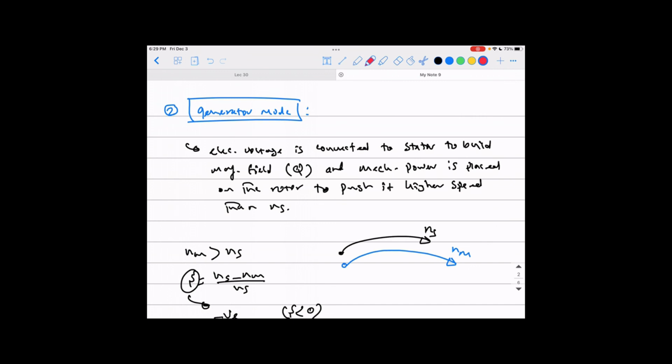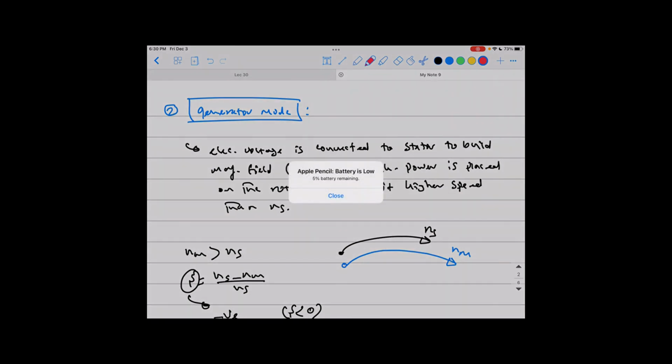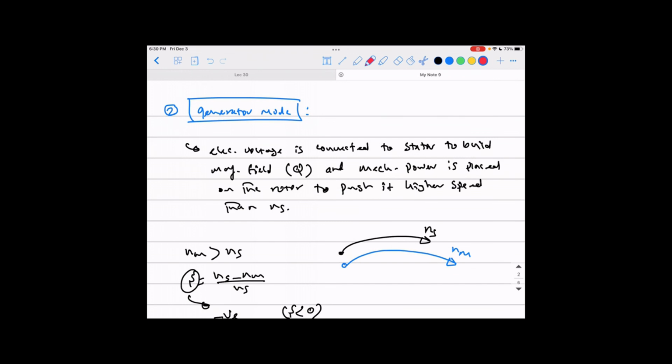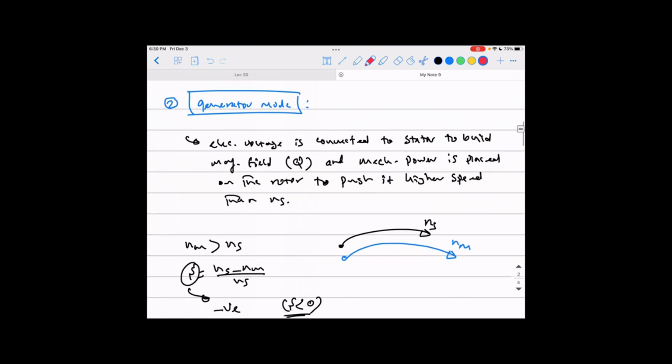It acts with almost the same theory of operation, but it's different because you have two sources, one on the stator and one on the rotor. With a doubly fed machine like that, you can work it out to have a Q output, because you have a different source on the rotor that can build your magnetic field.